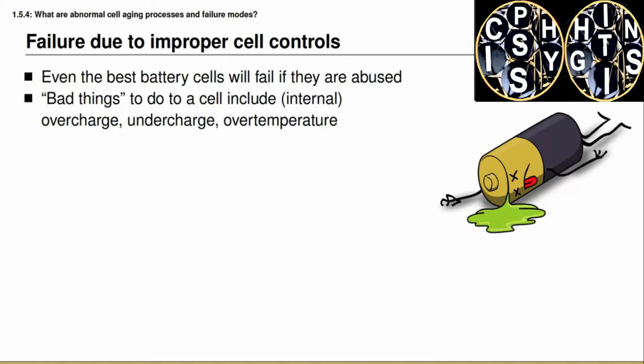happening to the entire cell, but the real problem really is what's happening locally at some point internal to that cell. So it's possible actually to have local overcharge or undercharge or overtemperature at some point in the cell when it may not be obvious that this is happening by simply looking at what's happening measured outside of the cell. And that's one reason why present-day battery management system algorithms are conservative in how a battery pack is operated, and how perhaps some physics-based methods in the future might be able to extend that operating range to give more performance.